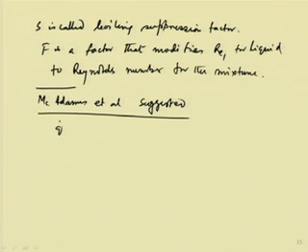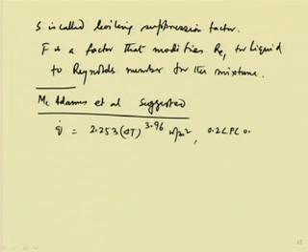It suggested that Q dot, the heat flux, is equal to 2.253 delta T to the power 3.96 watt per meter square, where 0.2 less than P less than 0.7 megapascal. So, it is a pressure dependency. This is a relationship for boiling of water at low pressure.